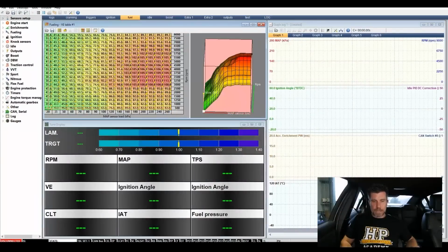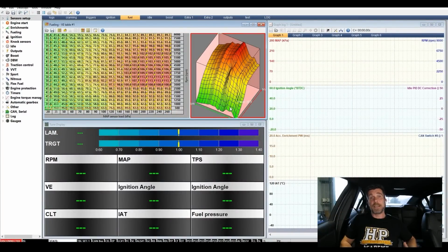Right, so the MegaLogViewer data, as I've mentioned, MegaLogViewer is helpful because it'll work with basically any .csv file. So as long as your data logger or ECU can generate a .csv file, you're golden. So let's have a quick look. The particular ECU that we were using for this demonstration was the ECU Master EMU Black fitted to our Subaru STI, and here is our volumetric efficiency table.